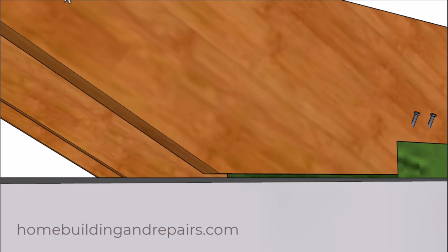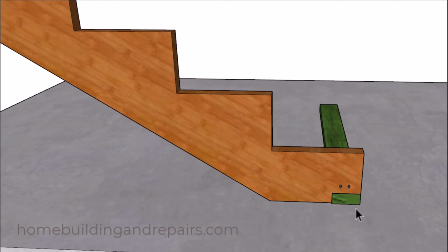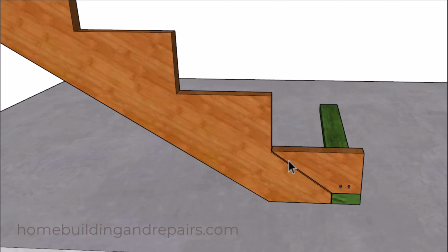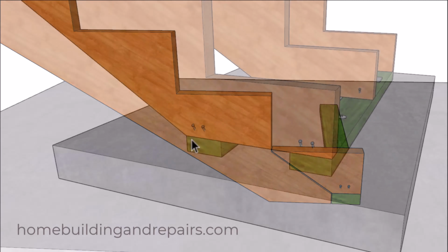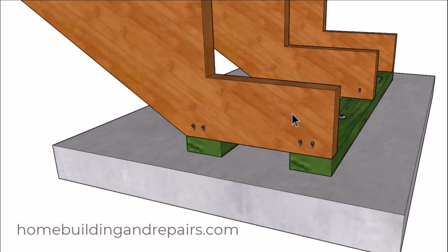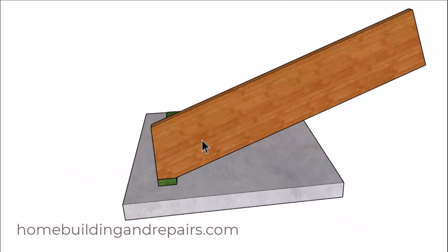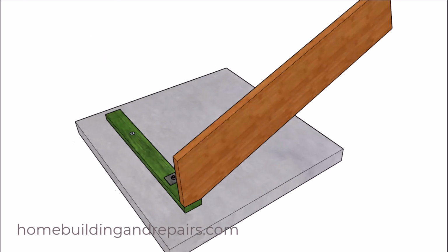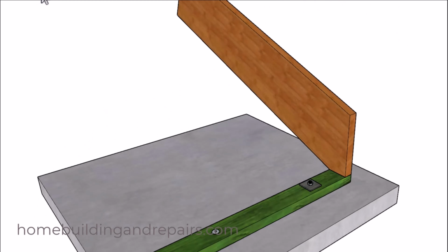And if you do have a gap and you're supporting everything at the front and there's enough pressure on the stair stringers, you could end up cracking the bottom of the stringer, just like this. And how do I know this? Because I have seen this before. So in my opinion, this is a superior assembly method that will allow the stringer to be supported in the back like a roof rafter. Right? If I was going to build a roof rafter, it would have some type of support like this, especially if it would be sitting on top of a wall and not like this.